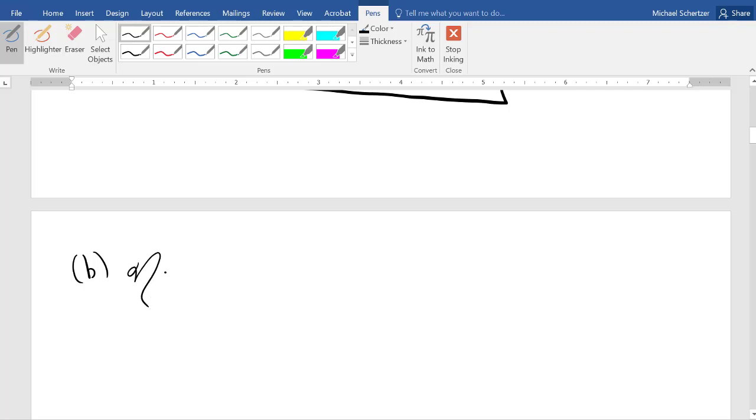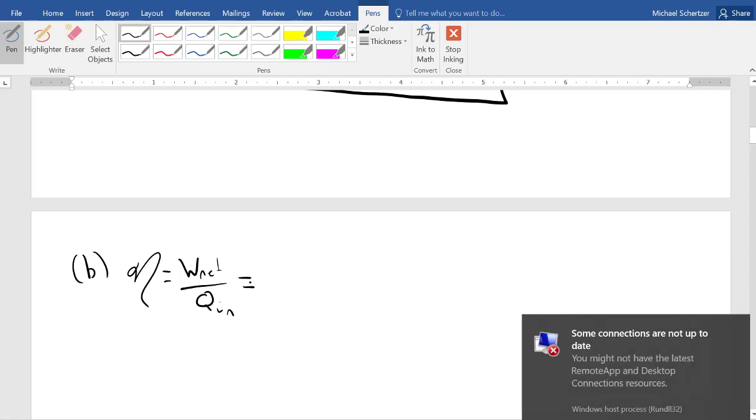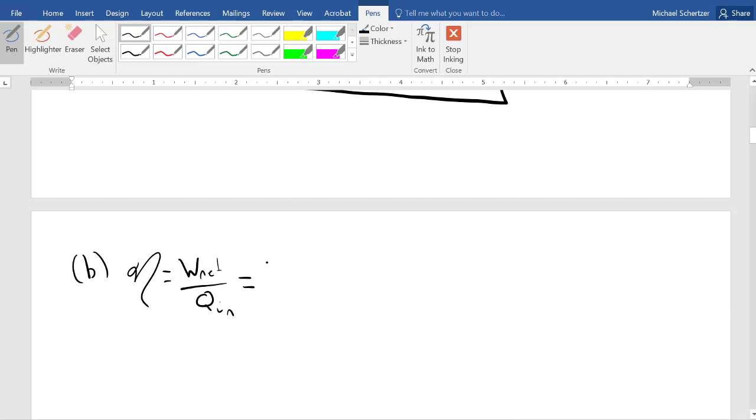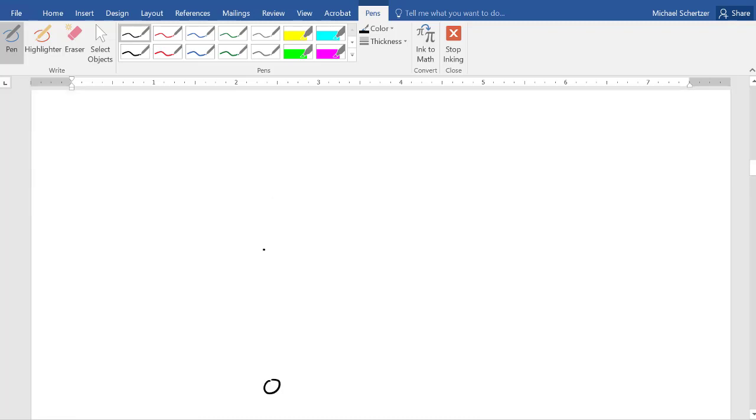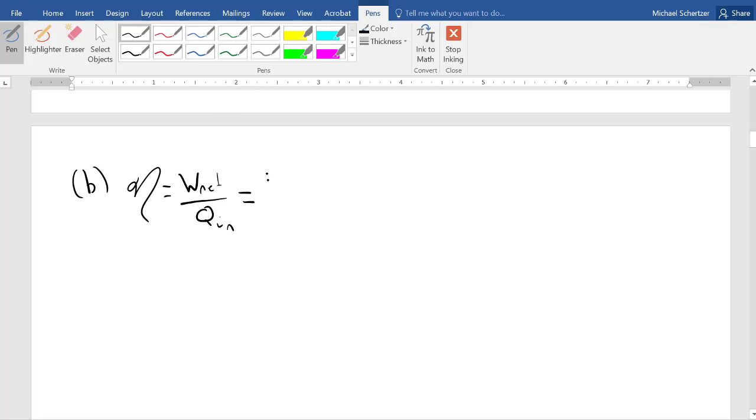we're asked for the thermal efficiency. So thermal efficiency, we know, is net work divided by Q in. But because the whole cycle is isentropic, it's all ideal, this is also going to be Q net over Q in. Now Q net is Q in plus Q out, so long as we're using the first law to get both of these terms. So Q out is going to be negative. I can divide all this by Q in, and this is going to be equal to 1 plus, I'll write Q out in red because I know it's supposed to be negative, Q out